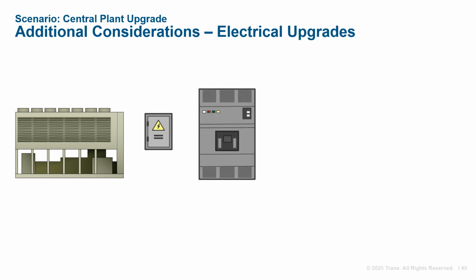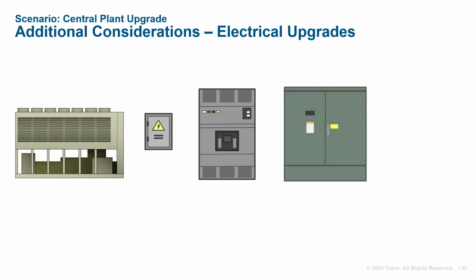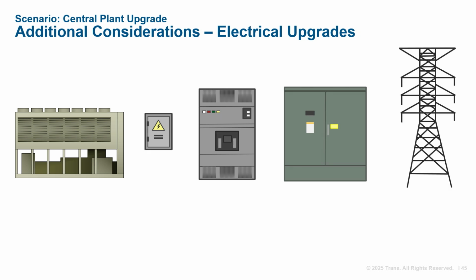If the distribution panel needs to be upgraded, you need to consider upgrading incoming service lines and equipment lead times. A transformer might need to be upgraded by the utility, which you could be responsible to pay for. For projects where the increase in power is extreme, the utility company may even need to upgrade the infrastructure to the entire neighborhood. Replacing wire can be extremely expensive, which could be required at one or more sections in the